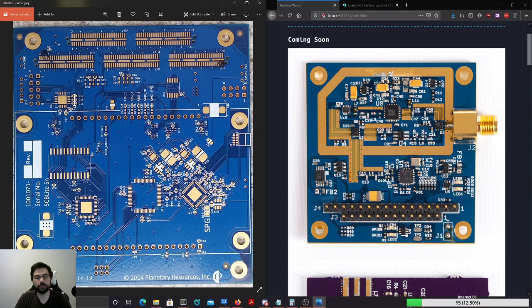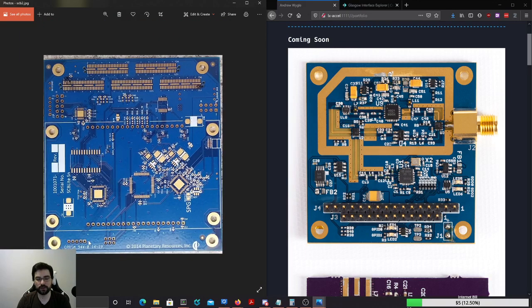So this radio had been tested by other CubeSats and found to work, and found that it drew about 5 watts of power when it was transmitting. That was the Microhard MHX 2400. By the time we came along, you couldn't buy the 2400. You had to buy the 2420. The 2420, spoiler alert, end of the story, draws 15 watts when you transmit. So we just tripled our power budget on our CubeSat that's like this big and has to run off solar panels. Not good.